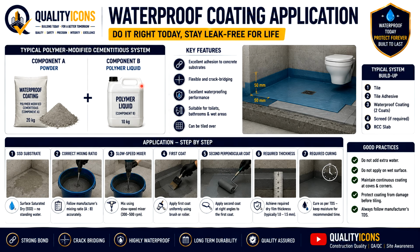The first requirement is the correct substrate condition. That means SSD or surface saturated dry without standing water. The components must be mixed according to the manufacturer's specified ratio using a suitable slow speed mixer. The material should be homogeneous and free from lumps. The first coat is applied uniformly. The second coat is applied in the perpendicular direction after a specified recoat interval.